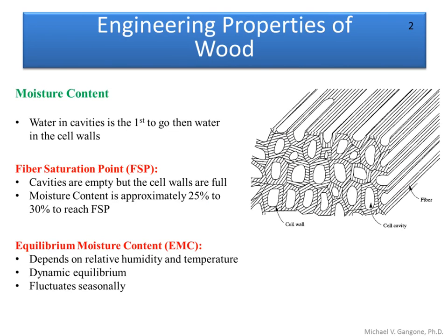Okay, once it settles at that 15% moisture content for that temperature and that humidity level, that is a moisture content that's now in equilibrium. All right, so it's not moving. It's a constant value that is being obtained at that particular temperature and humidity level. Now, as the temperature and humidity change, the moisture content is going to change. At a different temperature and a different humidity level, we might hit a different moisture content. That's really what equilibrium moisture content is. It's a moisture content that we reach equilibrium at for a particular temperature and humidity level.